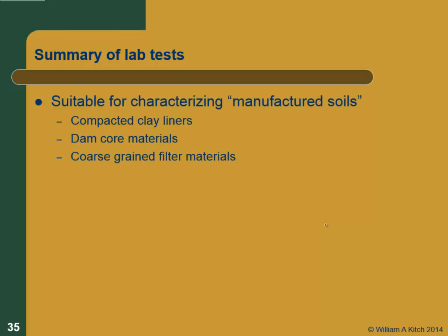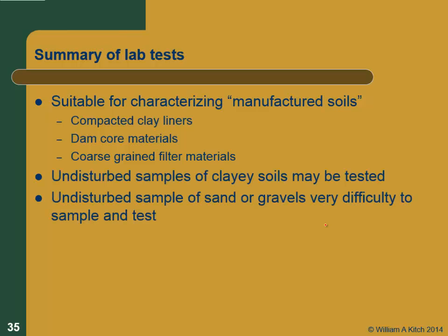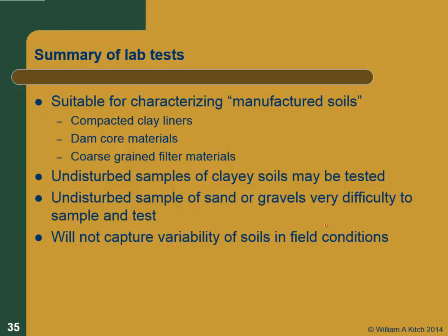Summary of lab tests. These are suitable for characterizing manufactured soils. You can get undisturbed samples of clay soils. You can test samples of gravelly or sandy soils, but there's a real question of what kind of sample disturbance you have and how representative they are of what's going on in the field. They will not capture the variability of field soil conditions,